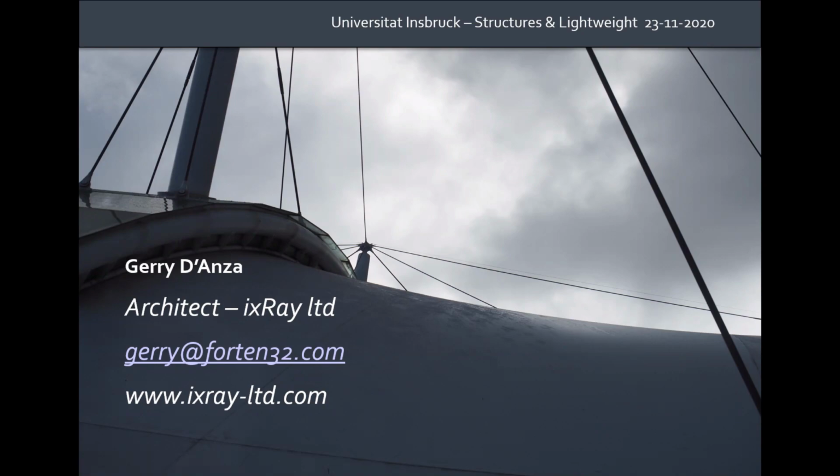And yes, the first thing that I want to do, since I think we are going to have a lot of hours of lessons, and we will talk about a huge amount of things, I want to introduce you first to the techniques that we use to do form finding. I think everybody has at least a basic idea what form finding is. The main problem is very simple. To make tensile structures or to use them as a structural element, we need to find a shape, basically a shape where the main two things that we need are the geometry and the pre-stress of the membrane.